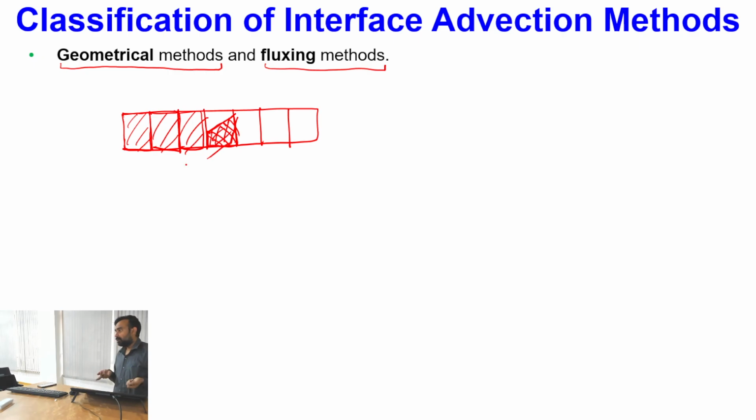Now, based on the velocity data available at different places, if I interpolate the velocity at all the corner points of this polygon, what will happen with the progress of the time step delta t? If I advect this entire geometrical object, the entire polygon, onto the next cells depending upon the velocity field, this situation is called geometrical mapping.